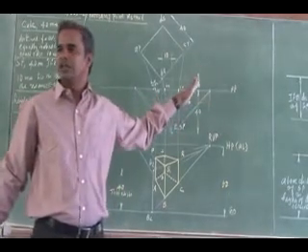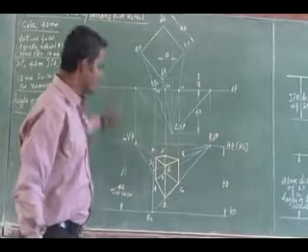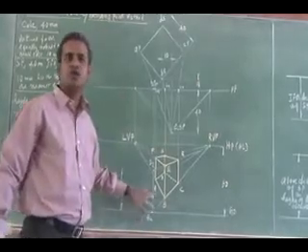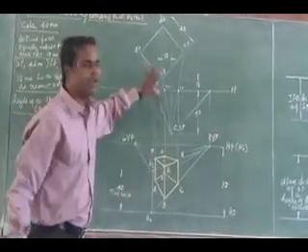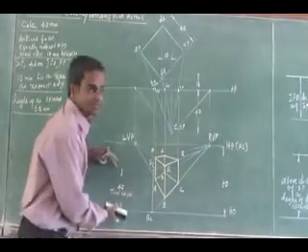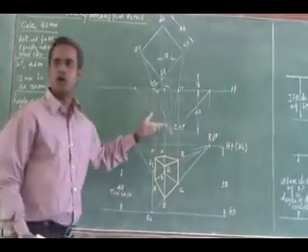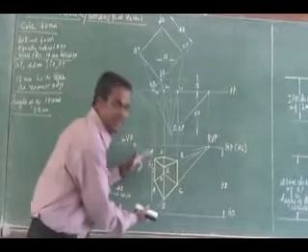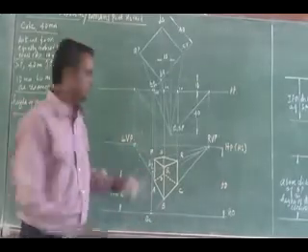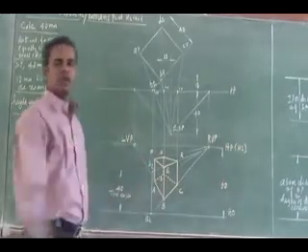Have any clarification? We go through this video step by step. For this, you no need to draw the front view. So you have to obtain the true height. If an edge is touching, no need to extend that edge directly. Perspective will give you the true height, that you can join to the right vanishing or left vanishing point.